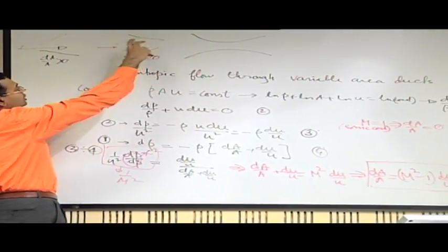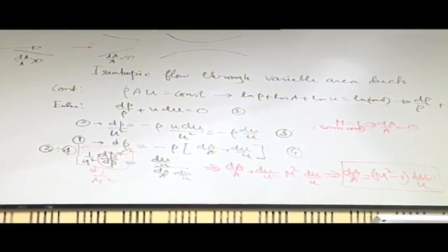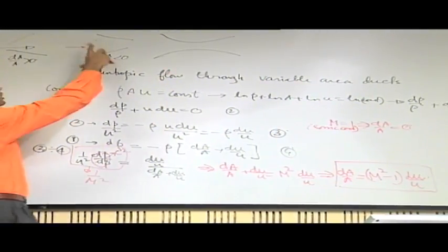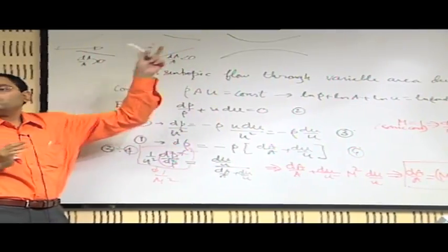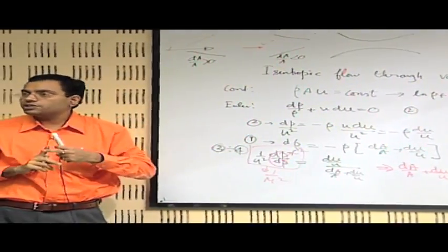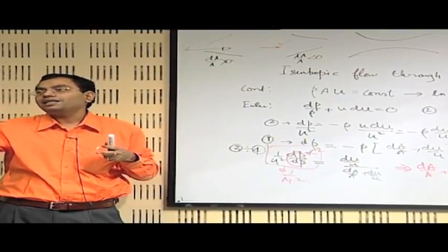This particular geometry, even if it is an incompressible flow, you see what is your target? The target could be to increase the velocity, that is why you reduce the area of cross section. These types of things where you have a variable cross sectional area with an intention of increasing the velocity, and therefore the consequence is reduction of pressure, that is known as a nozzle. So, if you have a nozzle, your target is to have an increase in velocity, but just this geometry does not ensure that it will be like that for a compressible flow. For an incompressible flow, area reduction will imply that the velocity will increase.